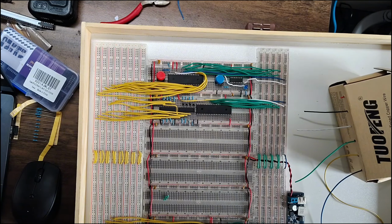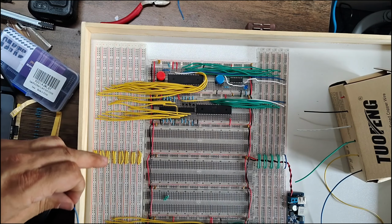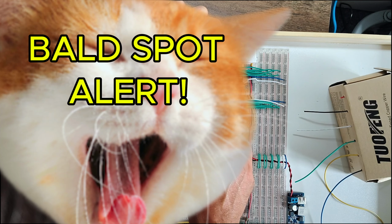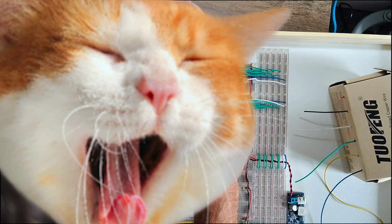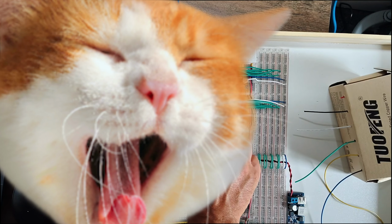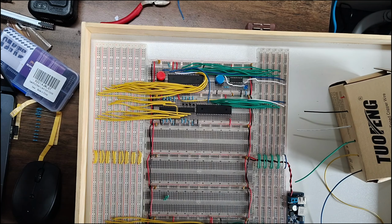The next pin we get to is a reset pin. Now, rather than having 2 reset buttons, it's actually easier just to connect both of them to the same button. So that wire runs around like this to the reset button for the main processor, and that's that done. And we're actually very nearly done.